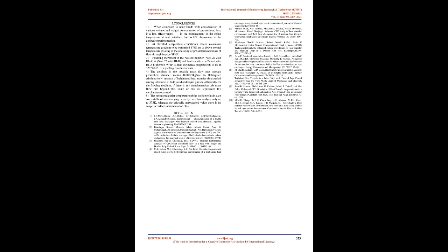In case of HIA, initially the temperature increases by 38 K at Re 500 with reference to without any insert, and thereafter the temperature difference decreases rapidly in the transition zone and eventually becomes almost negligible at Re exceeding 5000. On the other hand, with HIB, the temperature difference is 26 K at Re 500 and finally it becomes 0 at Re 3500.